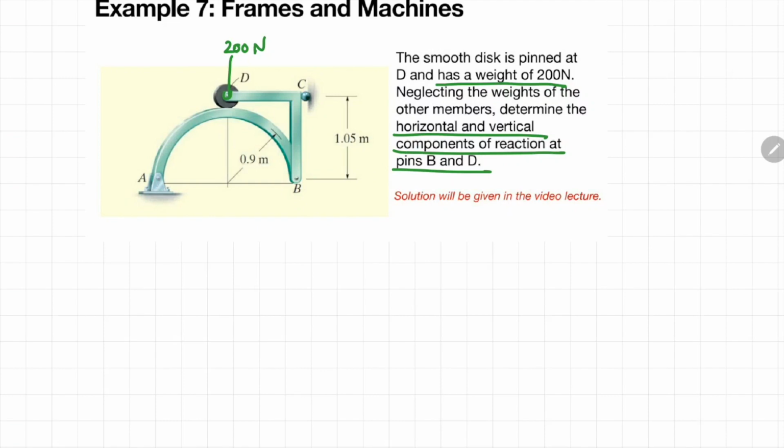Anyway, before we proceed finding all the reaction forces at pin B and also point D, let us draw the support reaction happening at each joint. Okay, so you know at this A is a pin kind of joint, so there are two corresponding forces, which is the vertical force of AY and the horizontal force of AX. Okay, and C is a roller kind of joint, so there would be one reaction force in the X direction. We're going to call it CX.